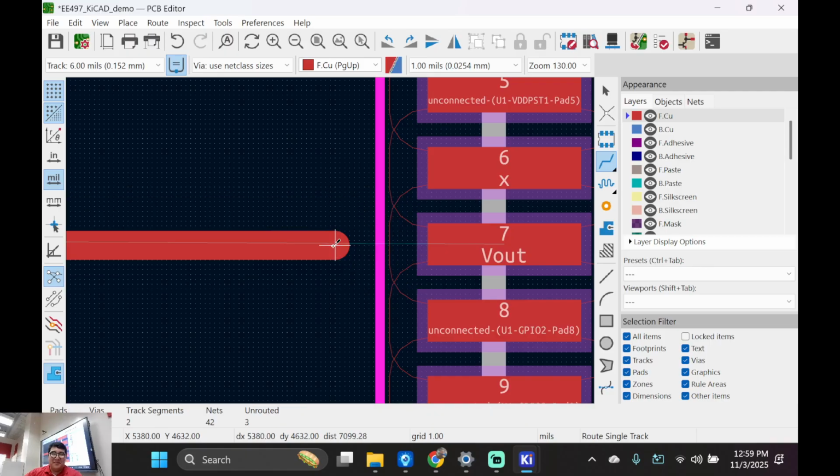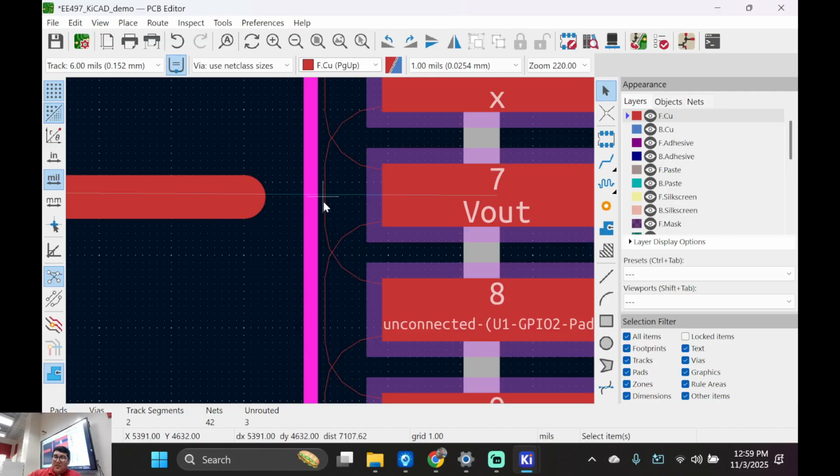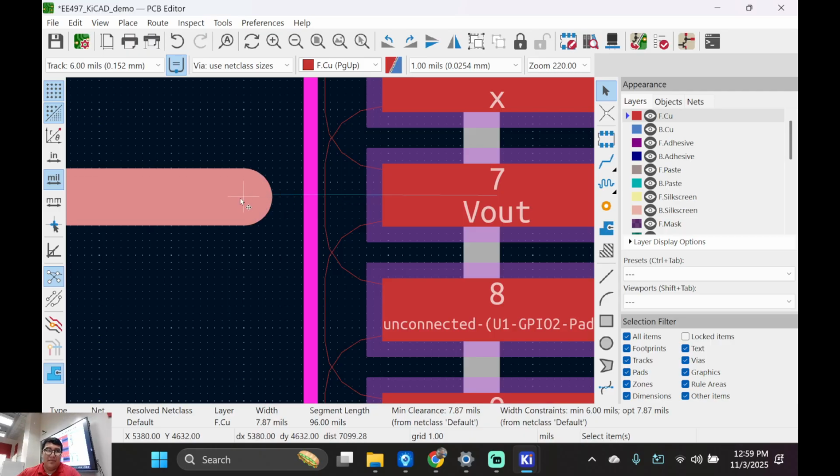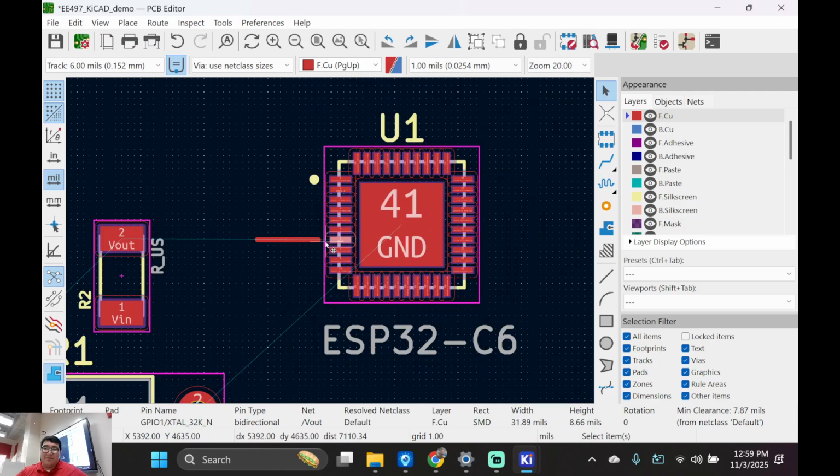Let me tell you what's going on. To the team that's using this chip right here, OSH Park won't do your chip. These red circles right here are your live design rules. Basically, these are circles saying, hey, I can't do it. It's going to break the rules. I was trying to draw a track right here, like a wire, but it won't let me connect it. Does that make sense? So this chip is not going to work with the manufacturer that I picked.